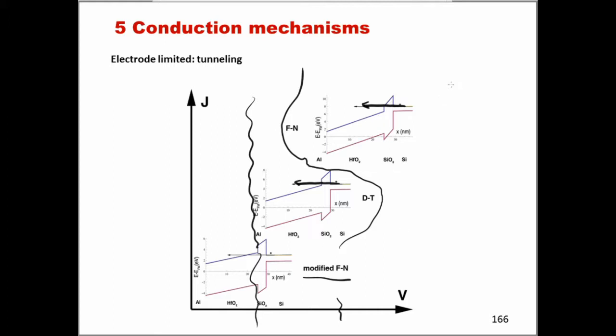So the JV characteristic that I will see could be analyzed in 3 regions, most probably. So the first one at very low bias due to modified Fowler-Nordheim. The second one could be most probably direct tunneling, and the high voltage one could be probably related to Fowler-Nordheim.